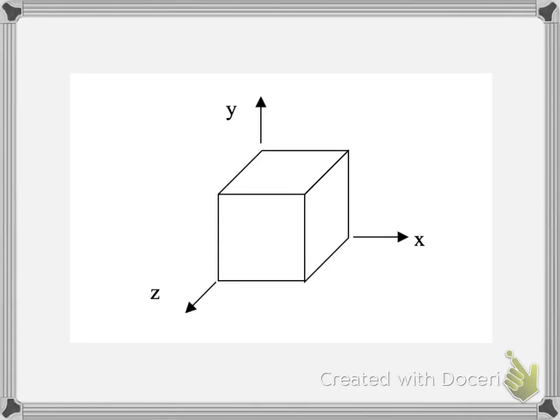Finally, we're ready to draw our stress block, and then we could do something like stress transformation, find the maximum stresses, whatever. So first thing, let's go back and look at all of the different stresses that we derived earlier, and we can start with normal stresses. And what we can see is that we're going to have our two normal stresses, and they come from P over A, and they come from M sub x C over I, both from acting in the negative y direction,